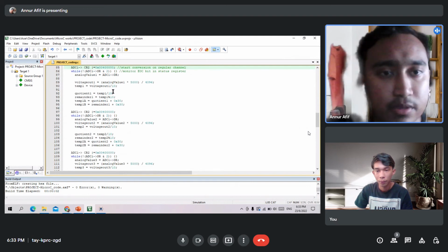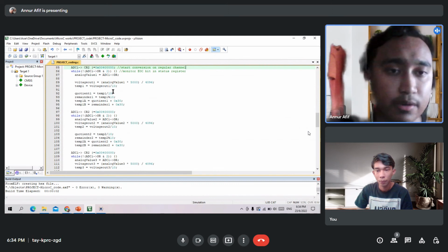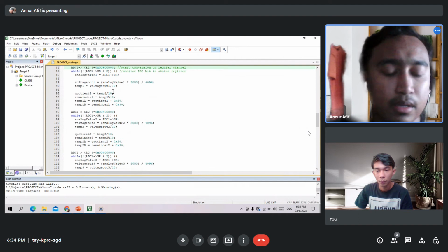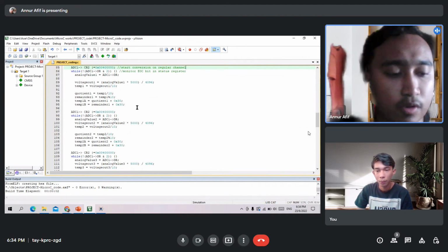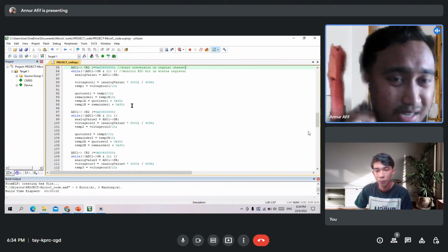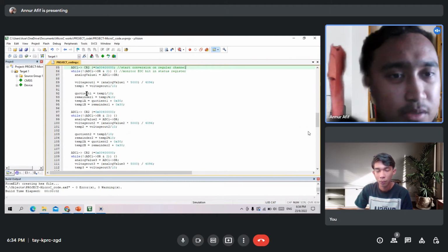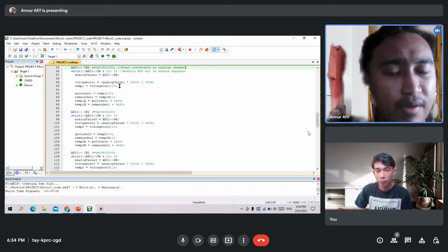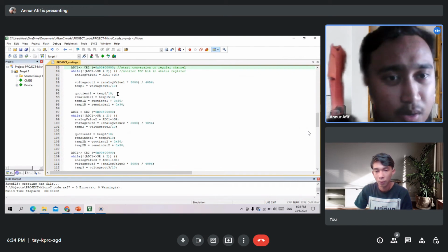The temperature value needs to be split into two parts, which are quotient and remainder, as from analog to digital, we need to convert the value to ASCII code, and ASCII code needs us to split them into two. So we split them into quotient and remainder. For quotient, we divide the value by 10, and for remainder, we modulo it with 10.